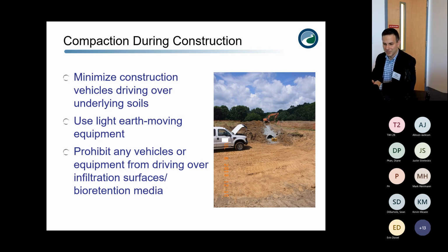So they drive down to the bottom. It's the quickest way to get to the outlet structure there. But we want to minimize construction vehicles driving over underlying soils. We want to use light earth moving equipment and prohibit any vehicles from driving over infiltration surfaces and bioretention media.